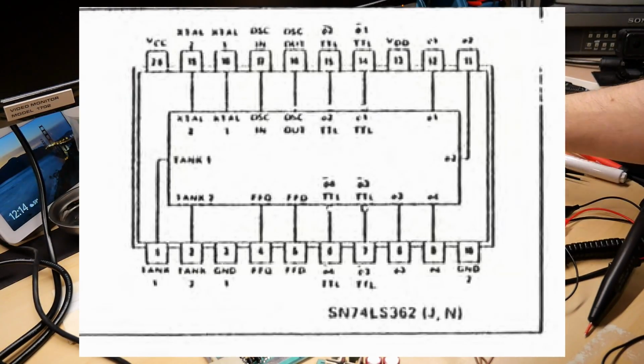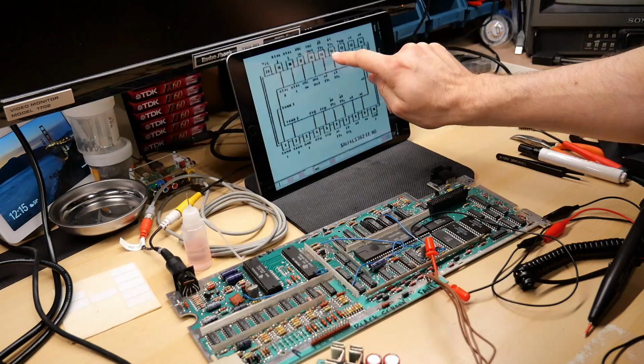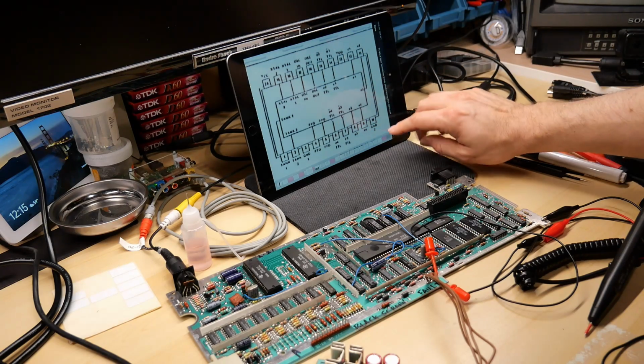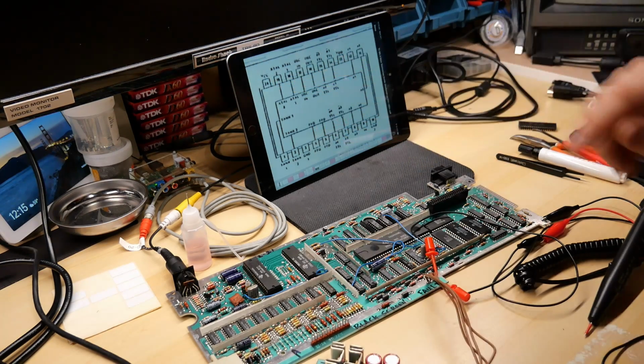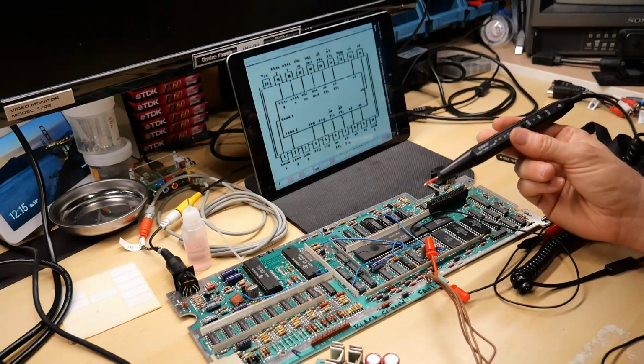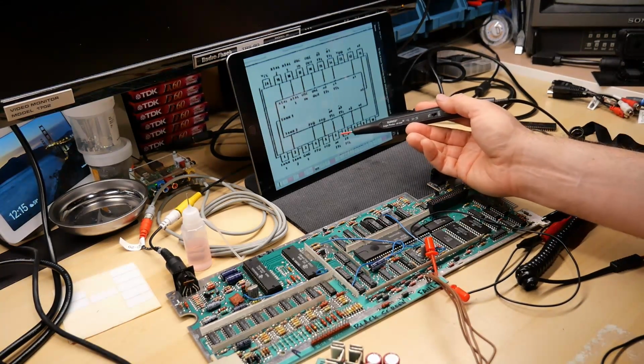So on the iPad in this document is a picture of the clock generator, and unfortunately it's so hard to read, but I can see there are 4 pins here that say TTL, so those must be the TTL clocks. And then these 4 pins are going to be the 12-volt clock output. Now there's ground, there's VCC. So I'll first start with the logic probe. We'll just listen for the beeping. In fact, I might as well go over these TTL clocks while I'm at it.